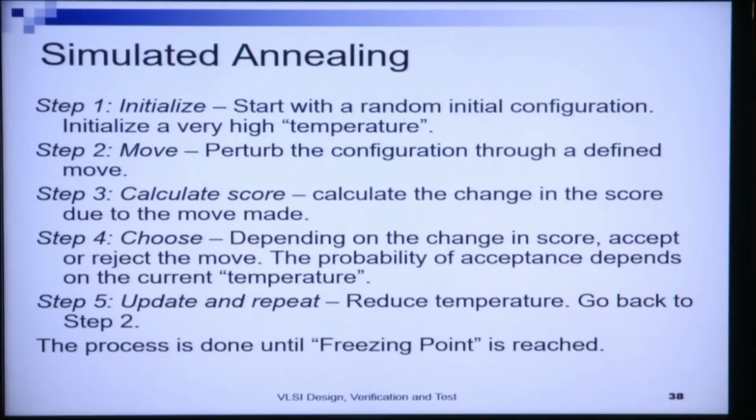Now from that initial configuration, I make moves over the state space. At each move, as I said, I either merge or split. With that merge or split, where do I go? I go to another merging of the temporary registers and operations to obtain a different allocation of the functional units and registers, and we will have an associated mux and demux cost, and due to that move from one state to another, in the new state I will have another cost of the solution.